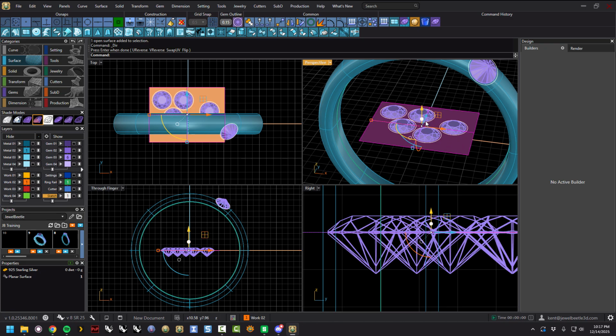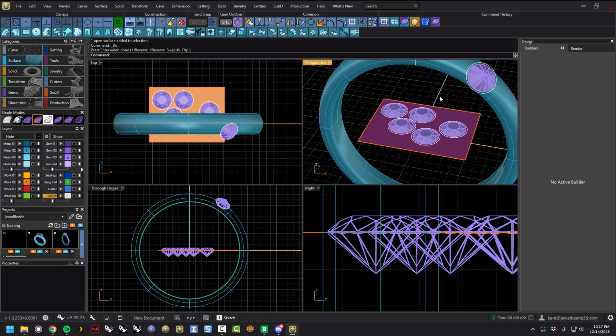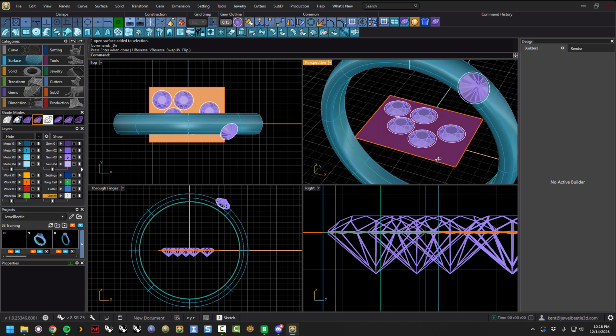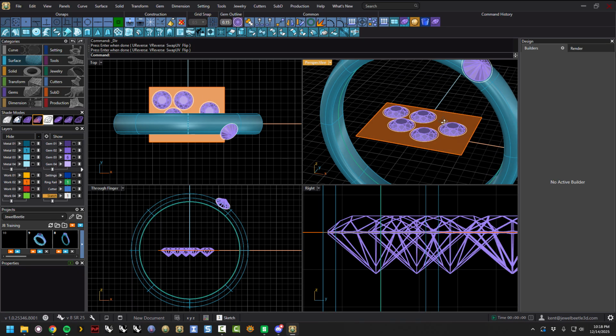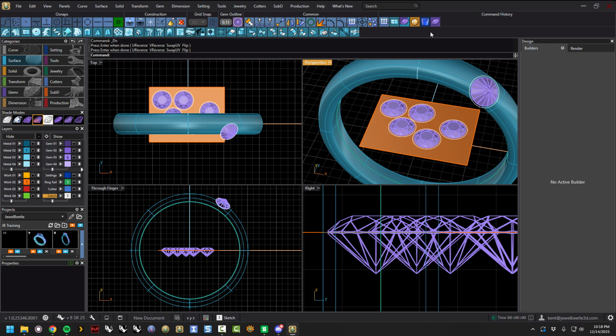And so that's how you can also tell. So before you even run the builder, you might shade a single surface this way and go, oh, these are wrong. This is the wrong way. I'm going to go to the direction and then left click on here and hit enter and flip it to be the right way. Okay.